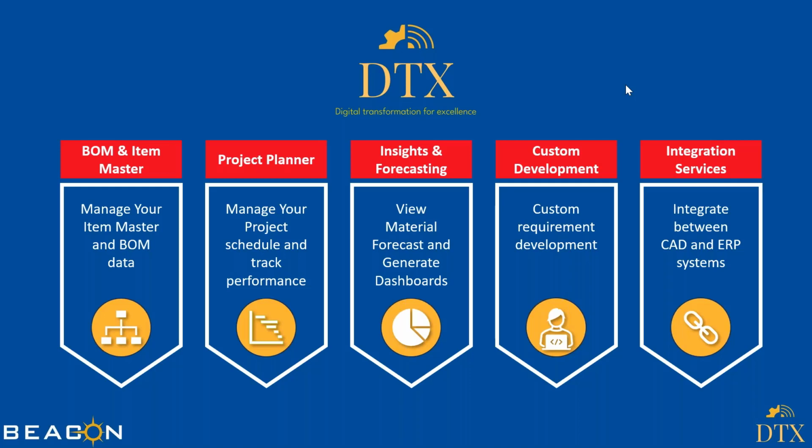So, starting with the conventional BOM management, which is the agenda for today. Conventionally, BOM creation happens with the help of CAD, extracting the bill of material with the help of the table within the CAD file. Either we create a CAD model, then take it to drawing, and then create a bill of material, or it could be done directly in Excel as well. Right, so that's the conventional method of creating a bill of material.